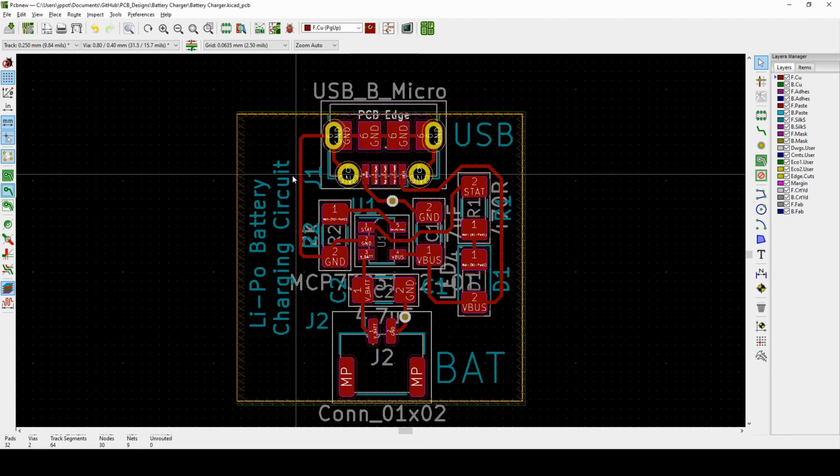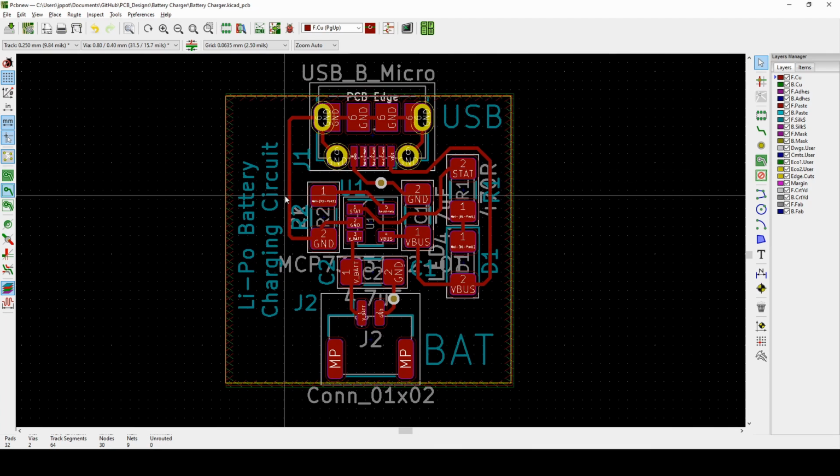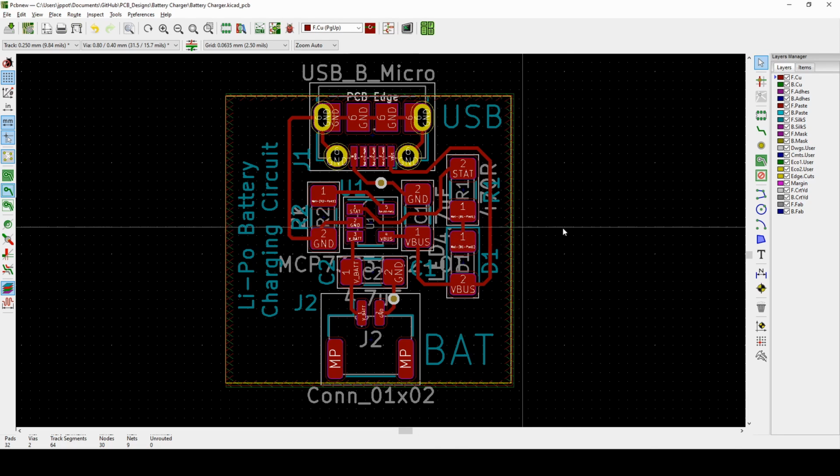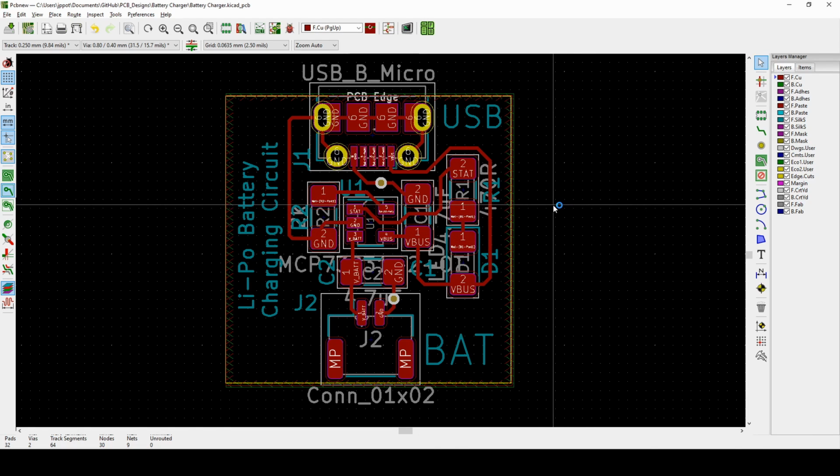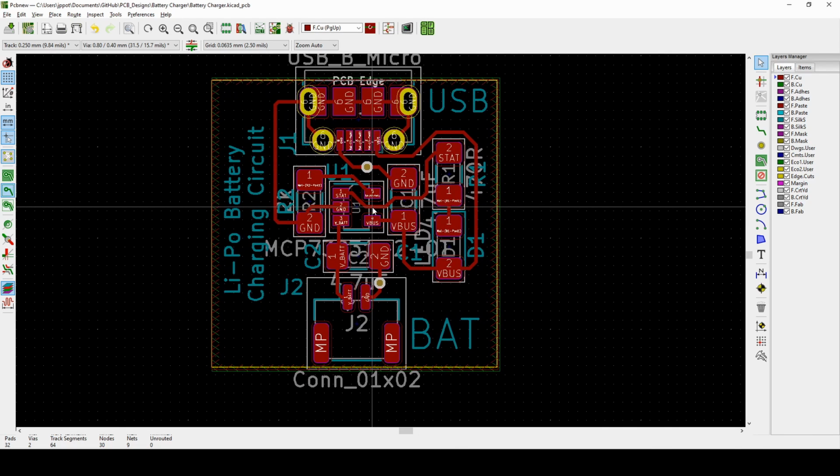But before we generate these files, there is a component missing on this PCB that is required for population on SMT machines. Those are called fiducials. Fiducials are basically just a reference point for the pick and place machine, so that they know where these components are according to certain fiducials.